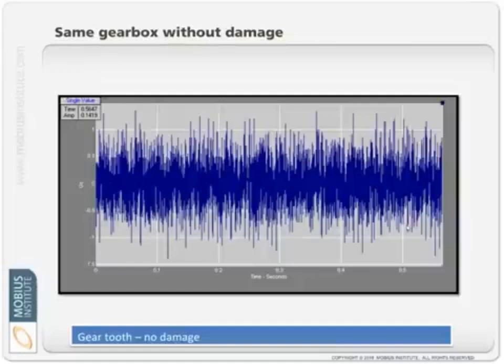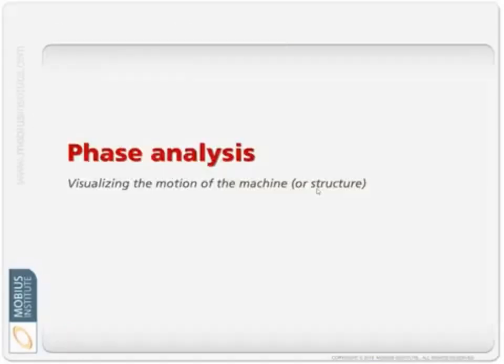But that waveform is what it should look like. Now, the amplitude looks really high, it's just that the scale is different. So that vibration is just normal vibration, low amplitude, even though it's been made to look bigger. So if we saw a waveform like that, who cares? It's telling us that everything's cool.